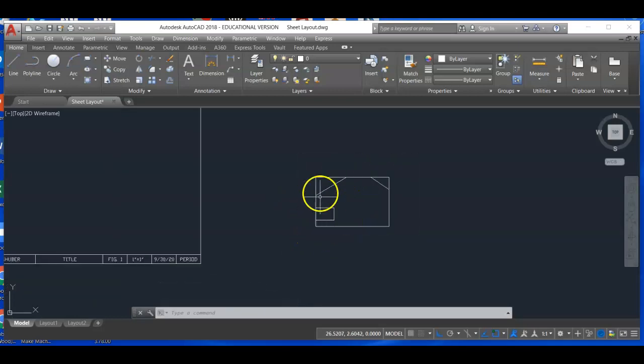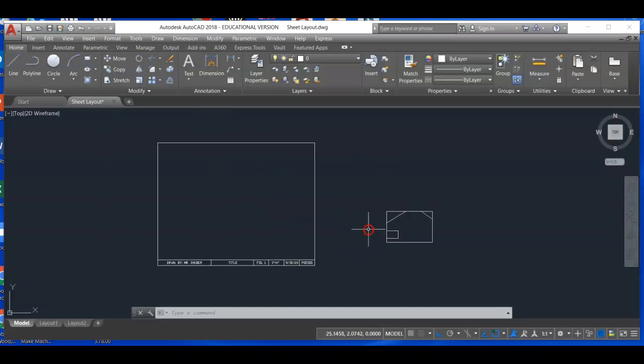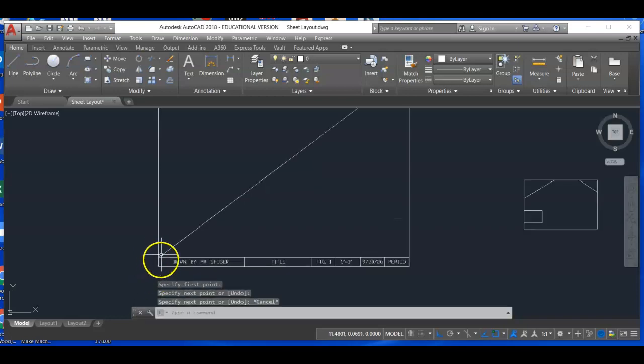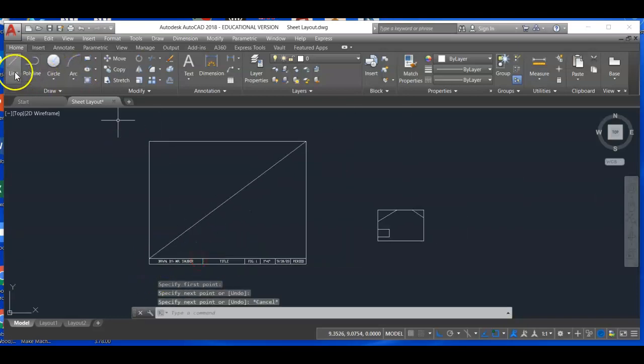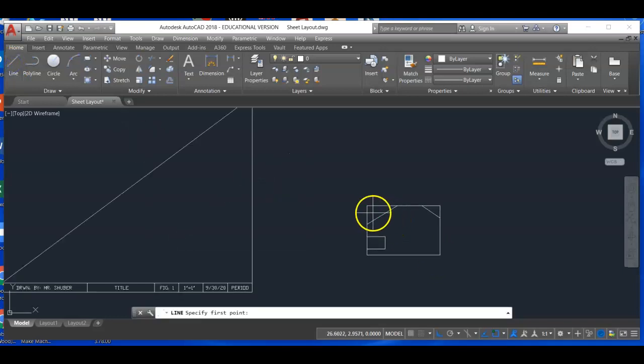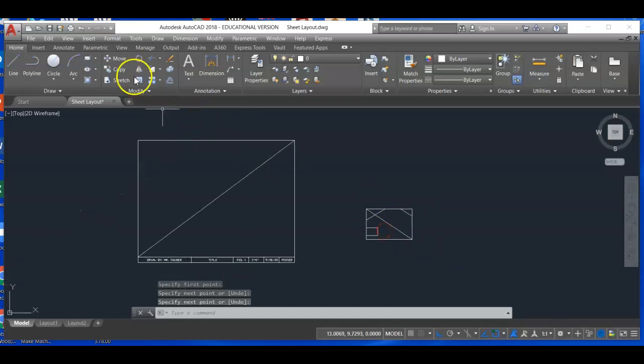Before I trim, like I said, let's go ahead and move. Now that we have the overall outside object created, before I clean it up, I'm going to center it within the title block in the border. I'm going to draw my little diagonal guideline that I like to do. Snap from corner to corner. Make sure it's at the top of the title block. And I'm going to draw another one on this object here from corner to corner. Notice I didn't trim that corner out, so I have that to snap to.